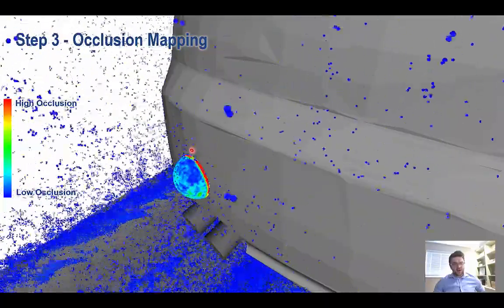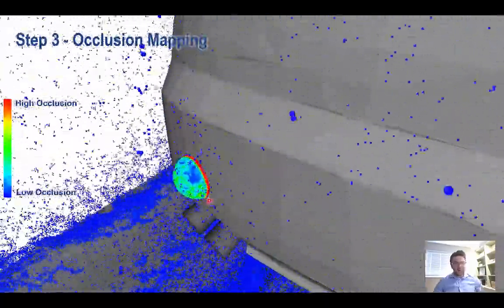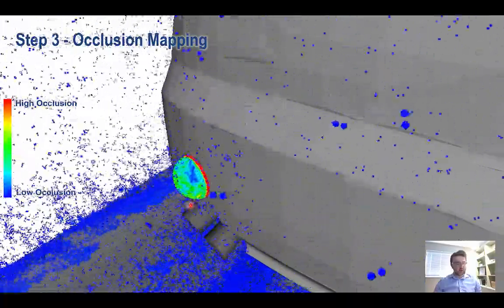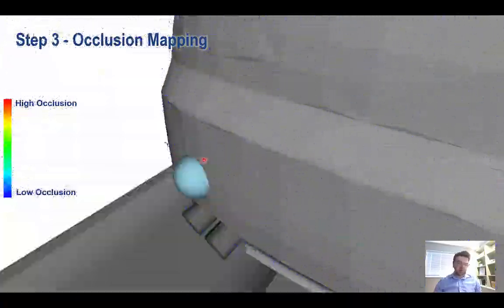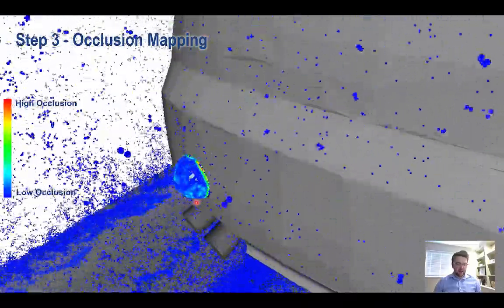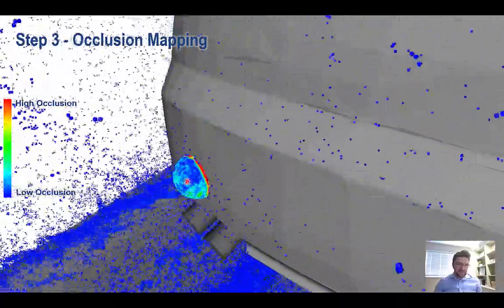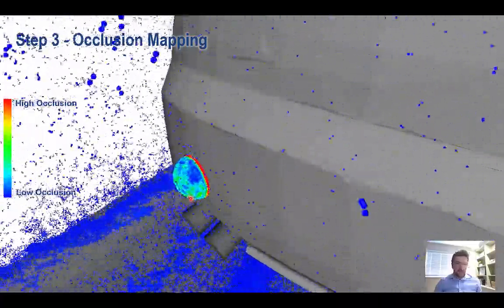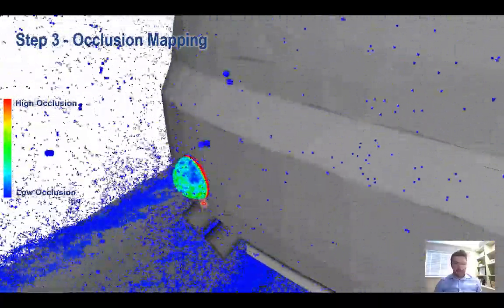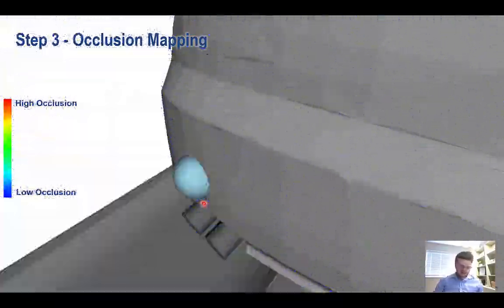So you can see the red region here is where particles are hitting the bumper, draining down and dripping around the outside of the LiDAR. Potentially we could build some feature here to redirect those drips, and we wouldn't have this red band form anymore. Regardless though, we do still have a very green picture overall, which means quite high soiling for the base state. So we need to do something to improve upon this.